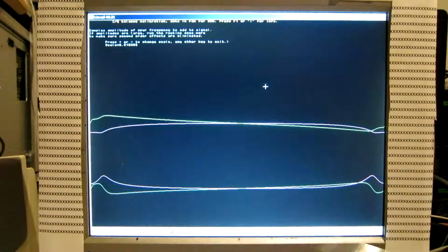And you can see we have now smooth shapes here. Probably to get this region accurately described, one would have to have even more segments. But it's not worth it. It's in the passband edge, and our interesting signals shouldn't be there anyway. We should avoid very strong signals near the passband edges if we want to listen to weak signals at the other passband edge. That's a limitation, and if you want to spend a lot of time on the calibration, you can avoid this problem, but it will require good temperature stability on the unit, because these are consequences of very sharp filters.